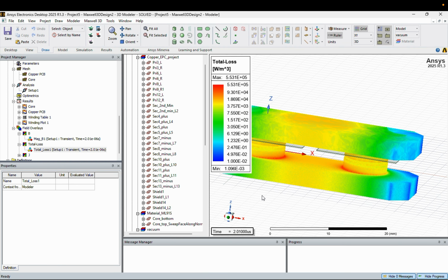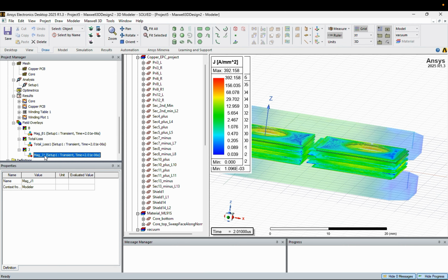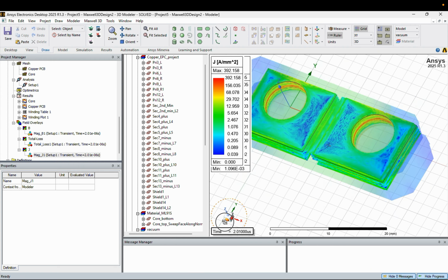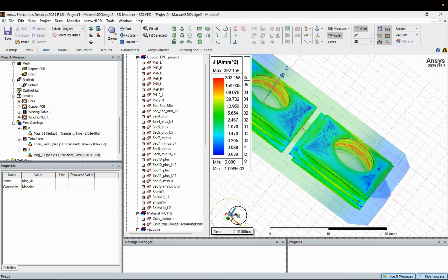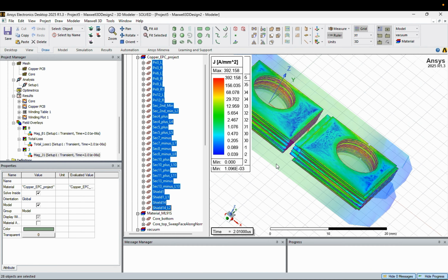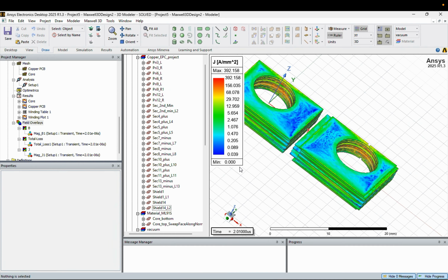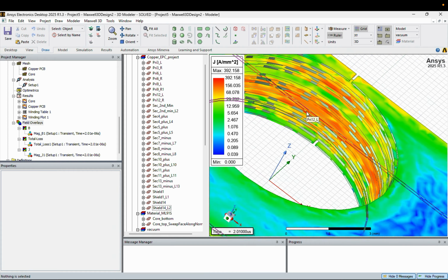That's what I did. And this is the current density of the wire or the PCB, where it appears as if it's like 5 amp, 6 amp to 10 amp per millimeter square, most of the places except for the center. Except for the center where it's much more red, that means it's getting hot.